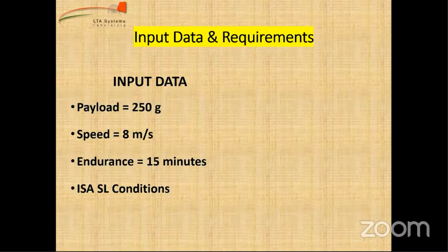And sir, sea level density is 1.125 kg per meter cube. 1.125 or 1.225? 1.225, sir. Yeah. So for our calculation, we'll use another decimal point, 1.2256. And temperature, I would ask all of you to check it again. What is the ISA sea level standard condition? 15 degrees Celsius. If you convert it to Kelvin, how much will it be? 273 plus 15? 288. Perfect. The ideal value is 288.16, but we are happy rounding off to 288.